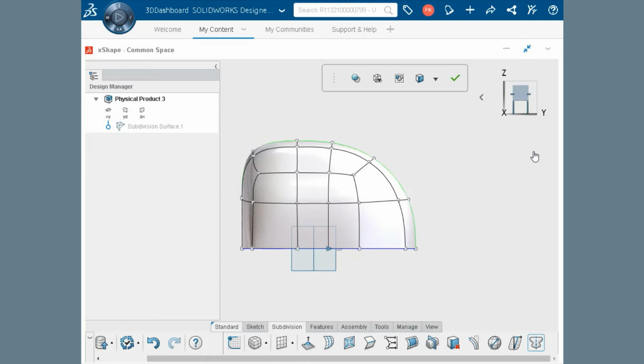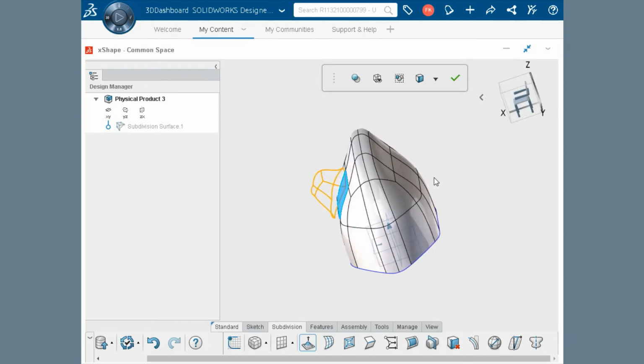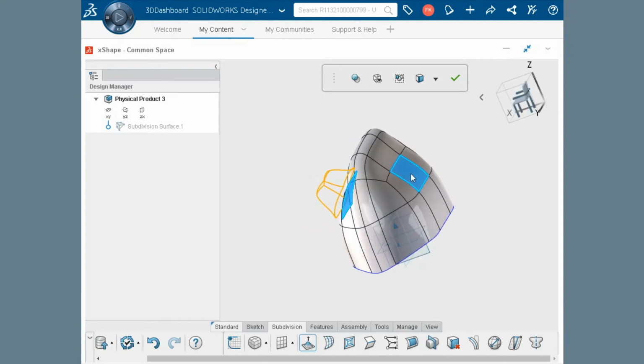After making some further adjustments, I'll disable Symmetry by clicking Symmetry again. This time we'll take a look at the multi-purpose extrude command. It can do many things, but this time it will be used to create a hole in the subdivision surface. Click Extrude and select two opposing faces, one on each side of the surface. After the first selection, it looks like it's adding material. The second selection changed it to removal. Toggle the command off by clicking the Extrude button again.